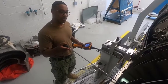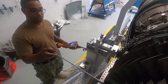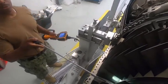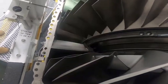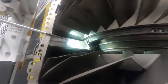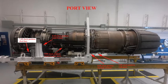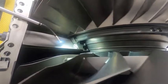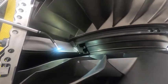Okay, normally we will come in through a borescope port, but for training purposes, we will give you a visual of what it looks like to come in through a borescope port. The top half of the engine has been removed for training purposes. Now, during the inspection of the fan section, we're coming in at the 7:30 o'clock position, which will show you the trailing edge of the first stage fan blades and the leading edge of the second stage fan blades.